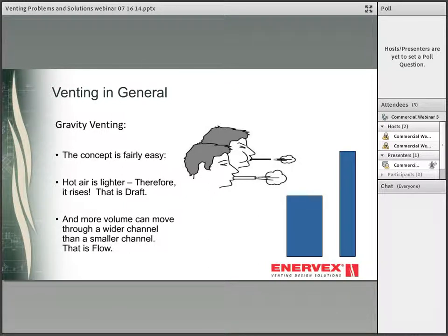The size of a chimney should be based on flow requirements, as any chimney size has a certain capacity in regards to the amount of flue gases it is able to remove safely. A good analogy is drinking straws. Blowing into a small straw is more difficult than blowing into a large straw, and you can blow more air through the large one than a small straw. A chimney works in the same way. A greater volume of air can flow through a larger flue more easily than a small one.